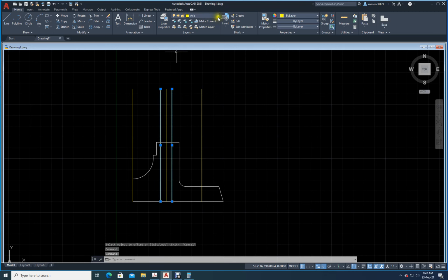Now just click on these lines and this line. Because they are on the axis layer, just transfer them to 0 layer. Okay, now press escape. So this top portion is no need, just trim it out. This is out, this is out. Okay, now you finished here.